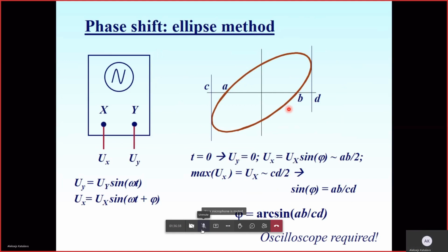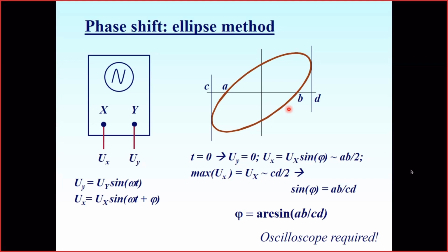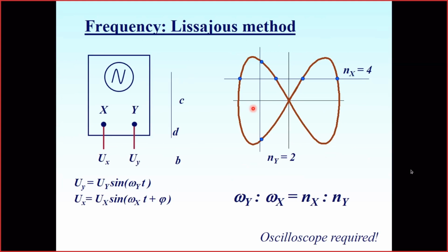Generally it may be line 2, but in the most common case, we see an ellipse. And moreover, usually it's very difficult in real measurement to get this ellipse still. It's usually a little bit rotating. Why is it rotating? Because we never have the same phase, because we never have ideal generators and ideal signal sources.